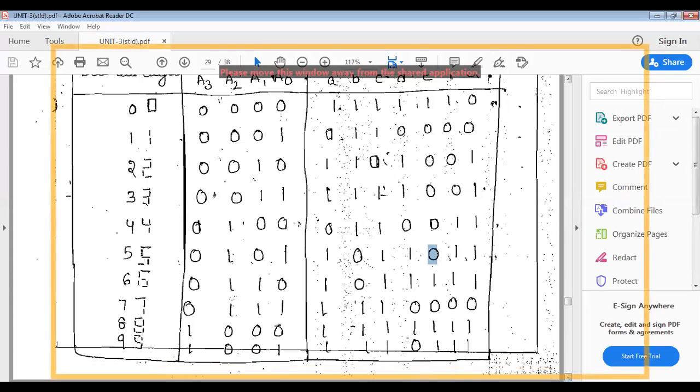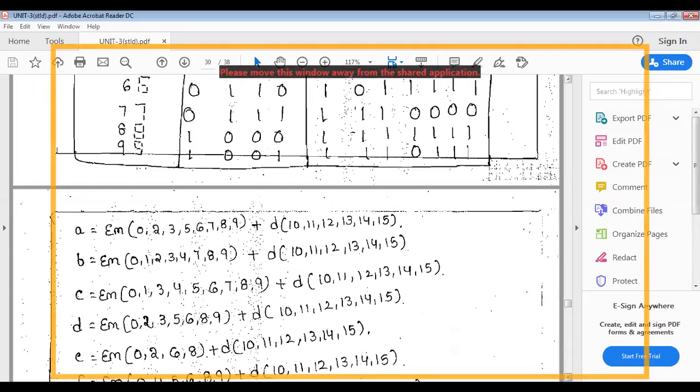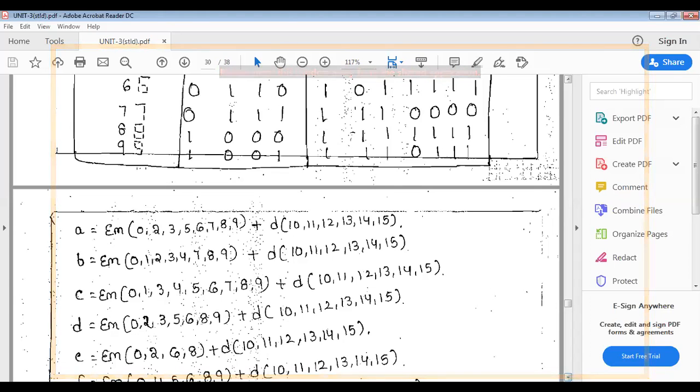According to that, you can design the BCD to 7 segment decoder. See why it is a BCD: the 4-bit BCD and the 4-bit binary are the same from 0 to 9. And for the 10, the BCD of 10 requires 5 bits, because each digit you have to write as 4-bit binary.